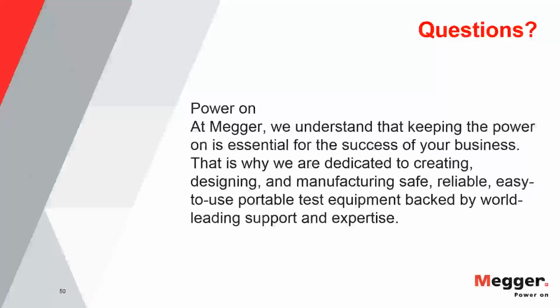Now there's of course online and substation-specific PD monitoring. So there's a big difference between offline diagnostics and PD monitoring. Megger has a few of these tools as well. This is mainly done by UHF and radio frequency measurements with devices that can be called handheld. They're not very, very large. And that is typically specific to substation equipment.